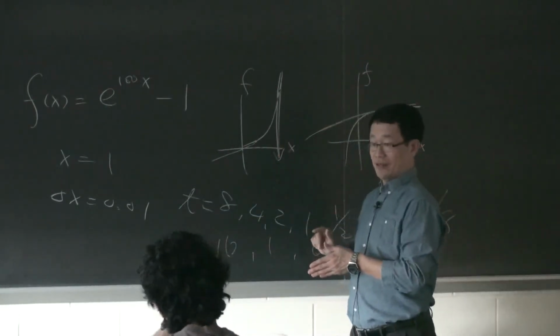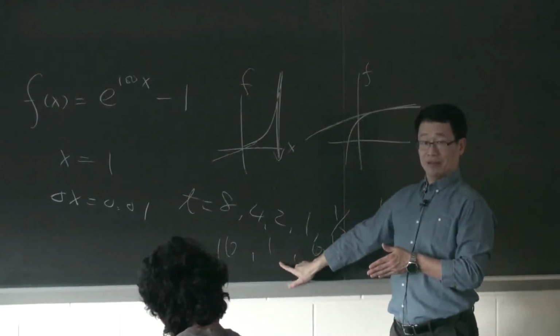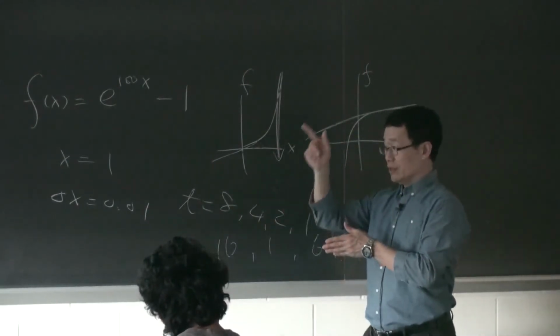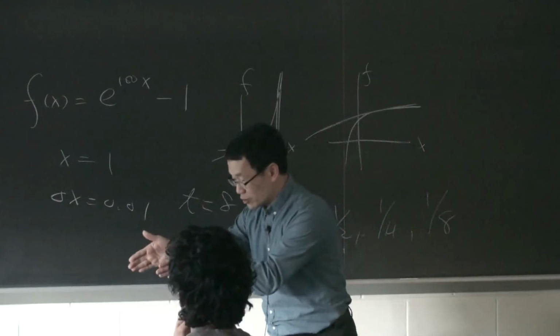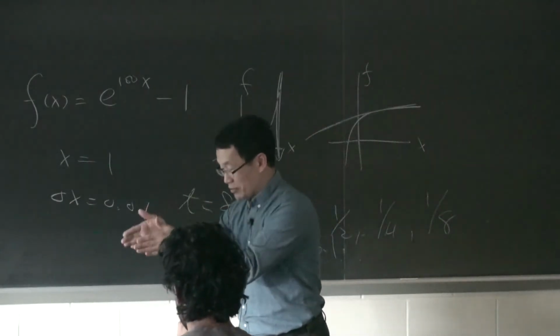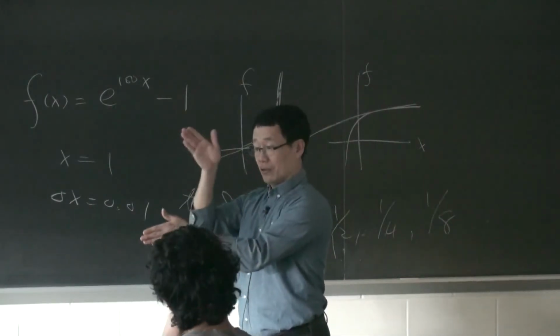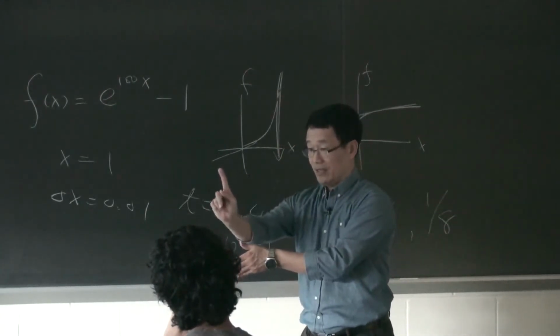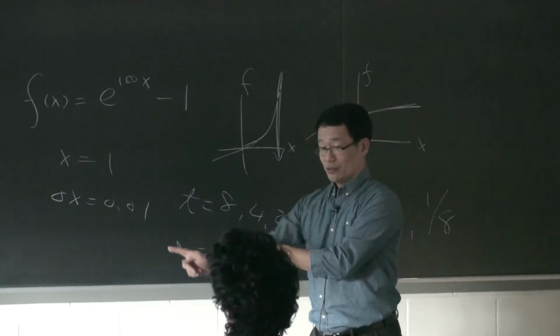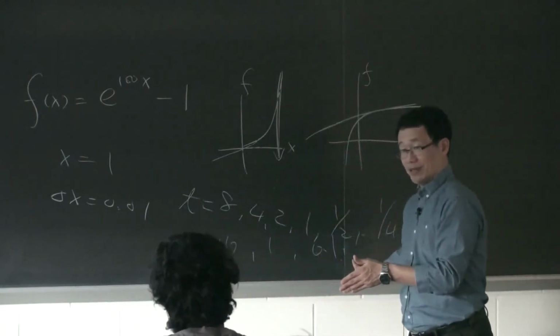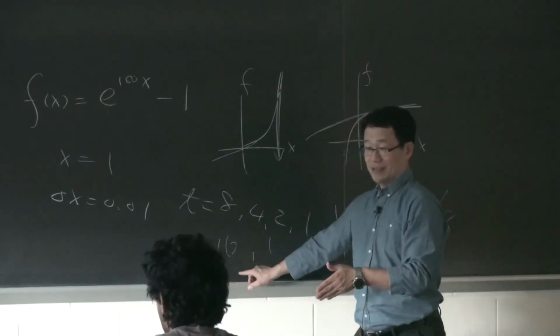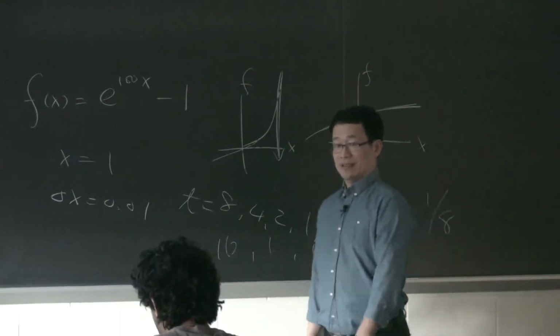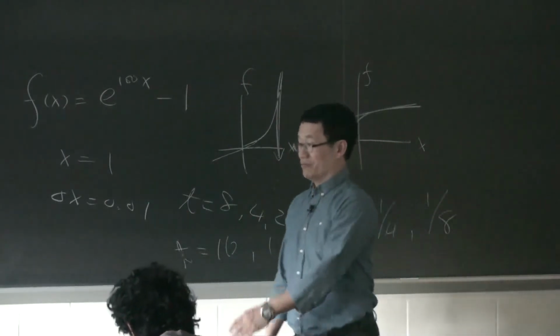So 1 has to be compared, because that's eventually when you are close to the solution and the problem is sufficiently linear. T equal to 1 gives you the correct answer in that quadratic convergence range. So you have to compare, not take T as a constant. That's guaranteed death, and that's probably where your NaN is coming from as well.